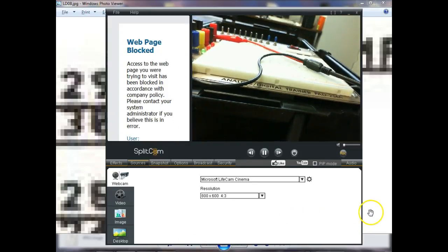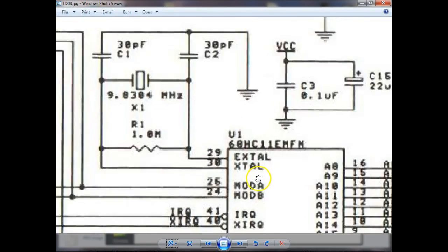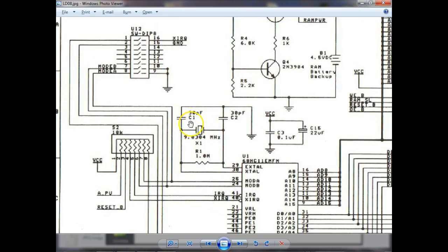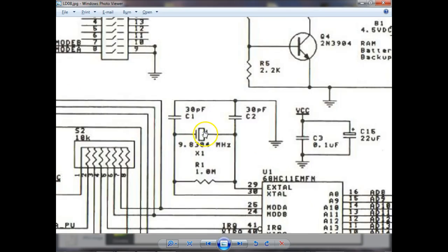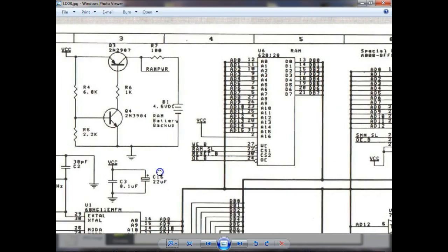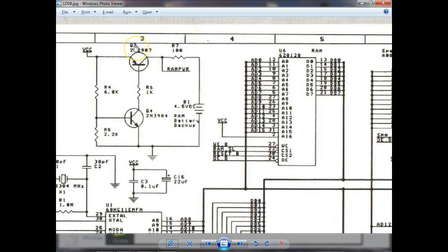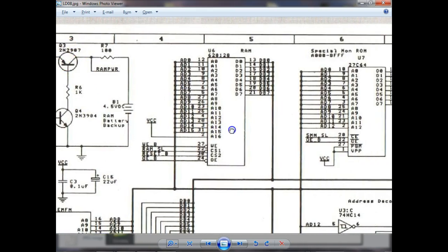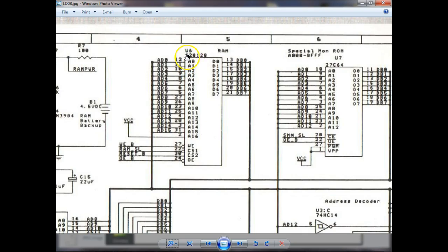So two of the things that we do on schematics is we do what? They assign it so C are for capacitors. So if I'm looking for C1, right, you understand, then I just find C1 labeled on the circuit board, right? You understand that? Transistors are U. I'm sorry, transistors are Q, right? You understand? Integrated circuits are normally what? U.